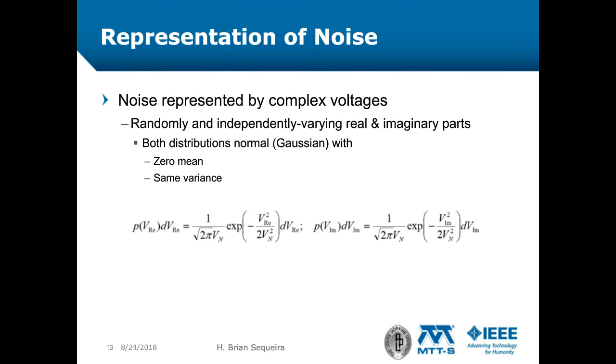One representation of the PDF by Gaussians implies that we have a large enough number of independent voltage samples to mimic a Gaussian distribution and to establish statistically meaningful quantities such as mean and variance. This implies that we observe the noise voltages over an interval of time large enough to collect a statistically significant number of samples. The variance of these samples multiplied by the time over which it's collected is proportional to the noise energy accumulated in the receiver.